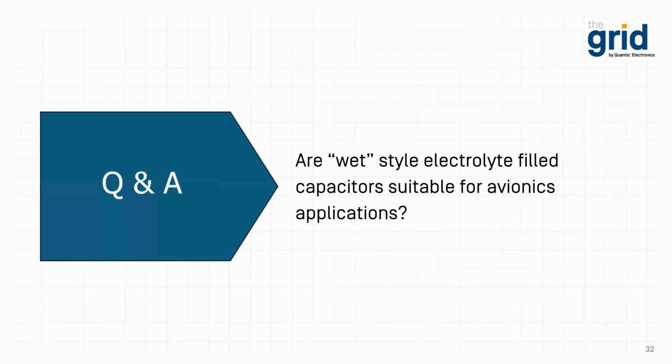However, the likelihood of the capacitor leaking when installed and designed in properly is almost negligible. There's ways to secure the capacitor to the board such that you're not imparting stress on perhaps sensitive terminations and things of that nature. So the short answer is yes, absolutely. Wet style electrolytic capacitors are perfectly suited for avionics applications.